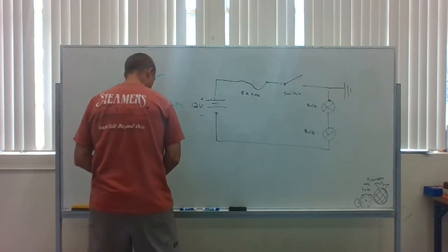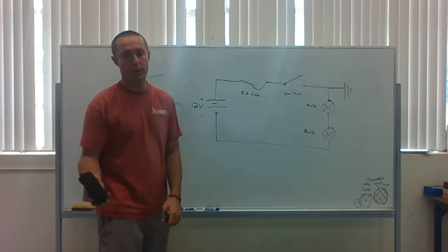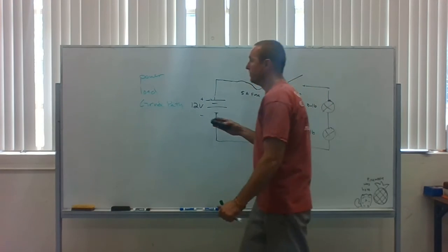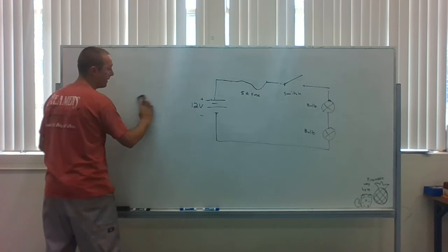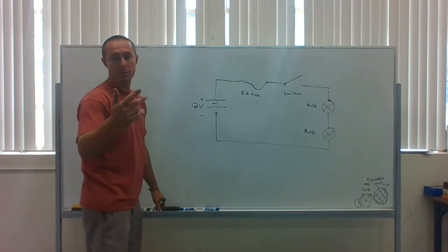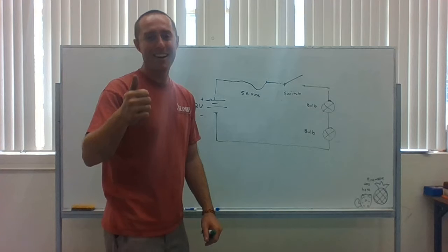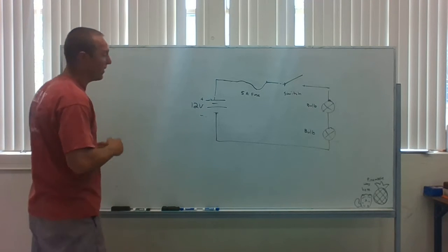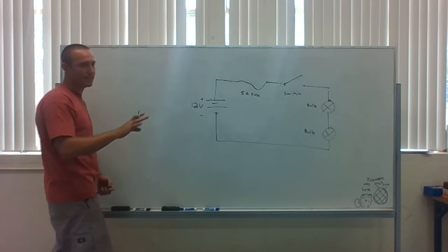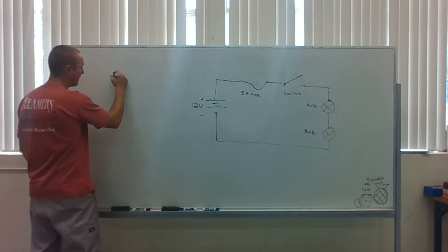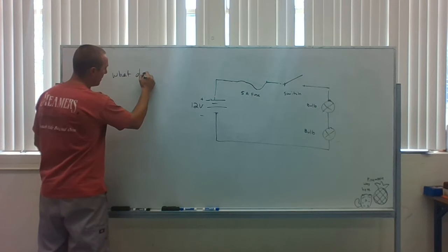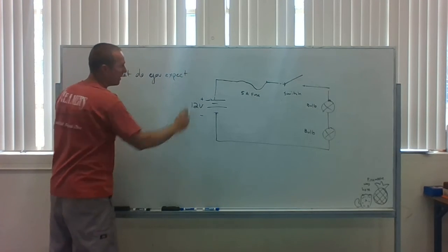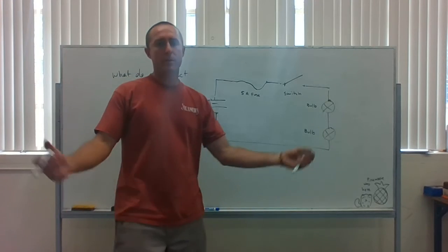Anytime when it comes to circuits, you've got to ask yourself 3 questions when we're diagnosing a problem. See, I told you, always threes. Threes: circuit, volts, ohms, resistance; threes: ground path, load, and power. 3 questions to ask yourself before you start testing anything. What do you expect? Like, what's the purpose of testing something if you don't even know what's going to happen?